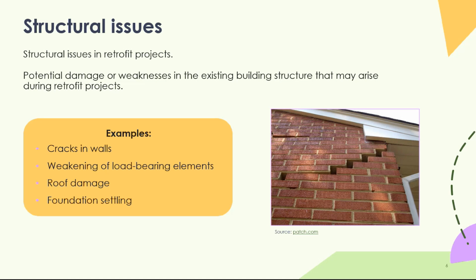So that idea that the property has to be in a sound structural condition before we can retrofit sounds really obvious, because it kind of is, but it's one of those things that you often won't know about until you get there, and then suddenly you're faced with this conundrum, and that's going to throw up additional costs, potentially in terms of remediation works that you will need completing before you can retrofit, and also time delays and contractor delays.